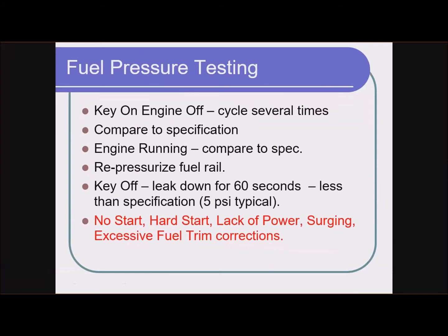The way I've done it in the past is by clamping off return lines, clamp the line off from the pump so that fuel can't run backwards, and see if that fixes it. Yeah, that should about do it for this slide, I think. So we're going to do a fuel pressure test if we have no start, hard start, lack of power, surging, excessive fuel trim corrections, and we don't come up with another reason for it.